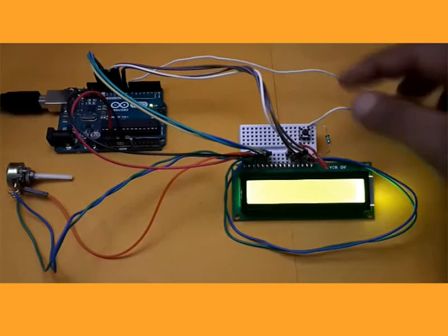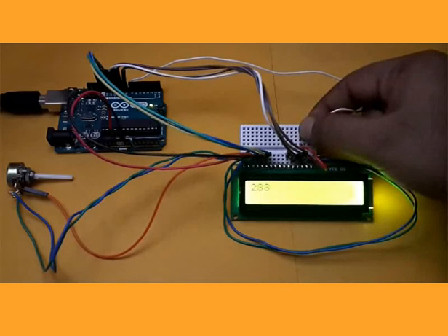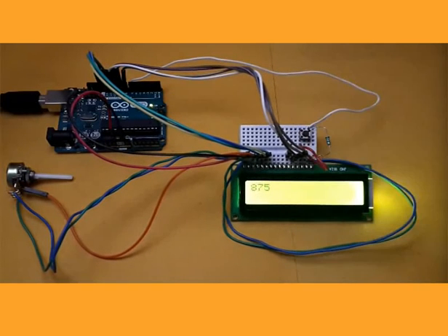Now I will press the push button. It didn't work as expected. We see a different count displayed here. Why is this so? This is because we specified the status for button pressed, but we didn't mention the status for button released. The output shows the incremented number based on the button pressed time.